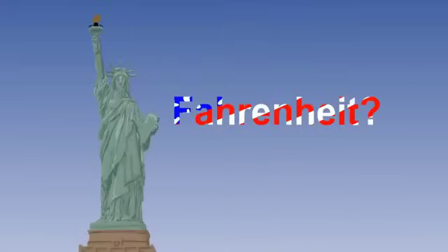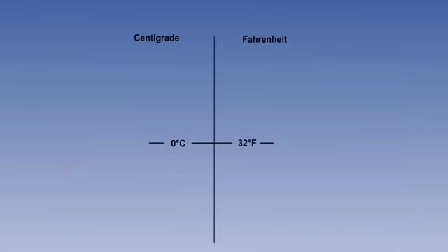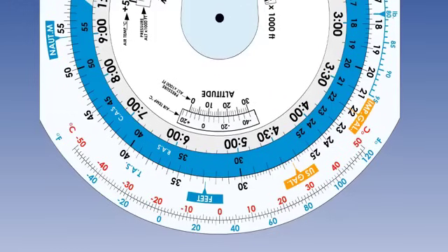The majority of the aviation world uses centigrade or Celsius as a temperature scale, but Fahrenheit is still widely used in the USA. There are 9 degrees of Fahrenheit temperature rise to 5 degrees of the equivalent Celsius rise. And 0 on the Celsius scale is plus 32 Fahrenheit on the Fahrenheit scale. There are formulae for conversion, but for simplicity, use the temperature conversion scale on the CRP5.